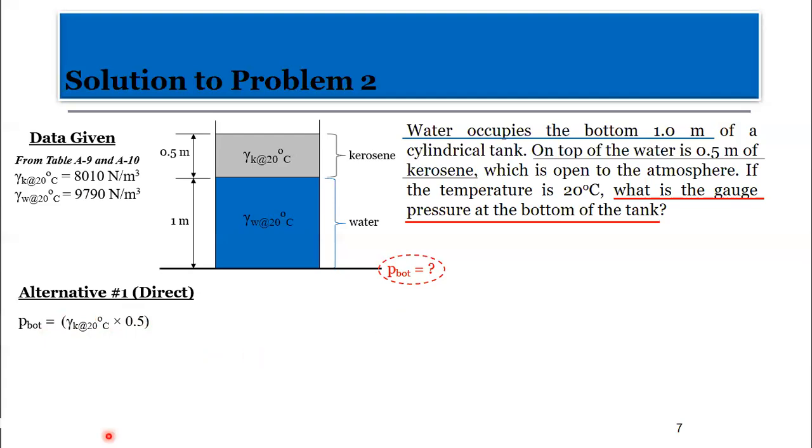So let me see whether I can write something here for you to recall them, okay? I'm saying that, remember, gamma is actually equal to what? Rho G, okay? And we know pressure is rho G H, okay? The hydrostatic pressure, okay? Good. So now that's the same idea.